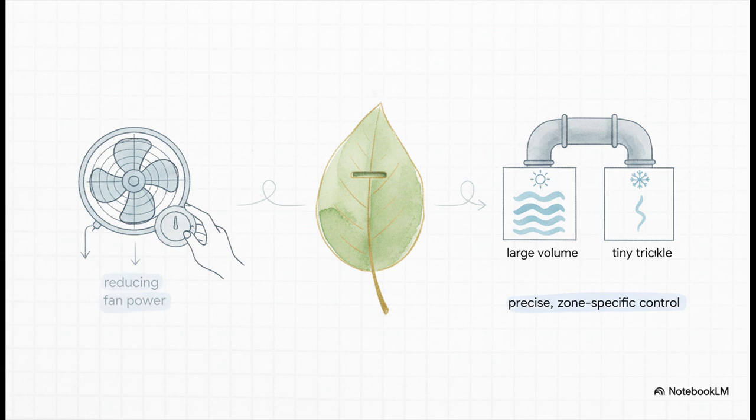Okay, ARE exam tip time. If you remember one thing, it's this. VAV equals energy savings. How? 2 ways. First, the main fan can actually slow down when it's not needed as much.